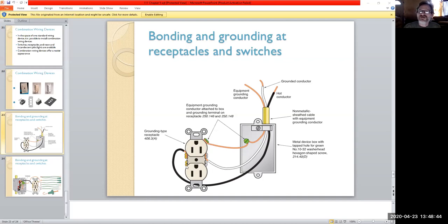So that protects, if anything were to happen to the receptacle, that's the outside of it, to keep it from bursting into flames, right? But this would be a very standard thing. Now, if you had more than one receptacle going into this box, like in this case, don't wire directly.